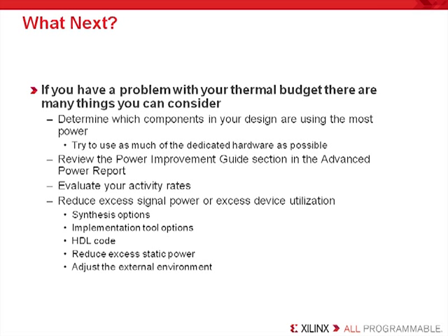You should evaluate your synthesis options. Enable settings which favor power optimization or area minimization. You can experiment with synthesis options which affect the design size, the number of signals, as well as the activity rate. Consider loosening the constraints when possible to limit the number of logic replications. That, of course, would affect your design size. Change the mapping threshold or add constraints to implement more of your logic into dedicated and lower power hardware blocks, such as block RAM or DSP slices.